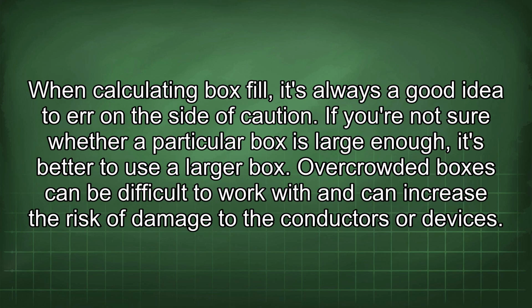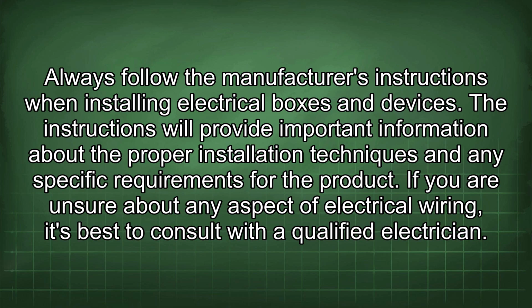When calculating box fill, it's always a good idea to err on the side of caution. If you're not sure whether a particular box is large enough, it's better to use a larger box. Overcrowded boxes can be difficult to work with and can increase the risk of damage to the conductors or devices. Always follow the manufacturer's instructions when installing electrical boxes and devices. The instructions will provide important information about the proper installation techniques and any specific requirements for the product.